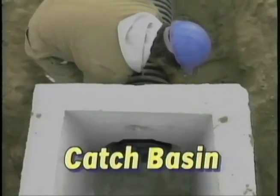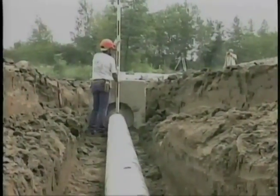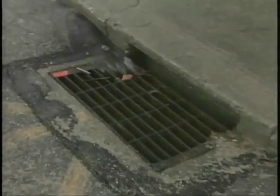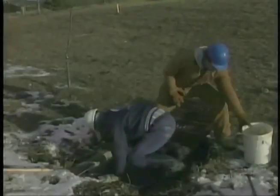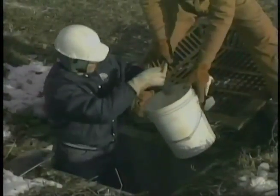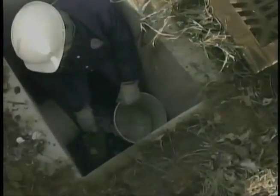Storm sewer installations are made using lead pipes that connect inlets and catch basins to the main line. Catch basins collect and direct surface water. Grate tops or drop inlets allow the water into the basin, and an outlet pipe directs it to a main line that dumps the water into a river, pond, or drainage area. Catch basins also make it possible for maintenance crews to access the storm sewer line to perform cleaning, flushing, repairs, or inspections. Maintenance crews have to clean catch basins on a regular basis because dirt and debris enter along with the water.